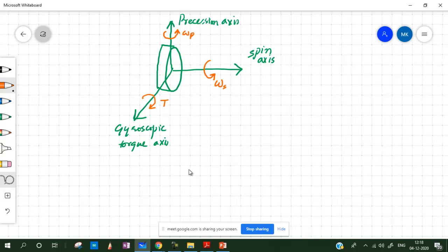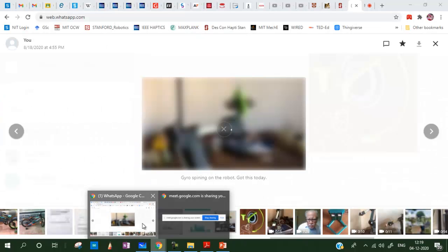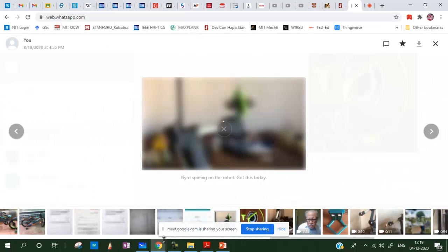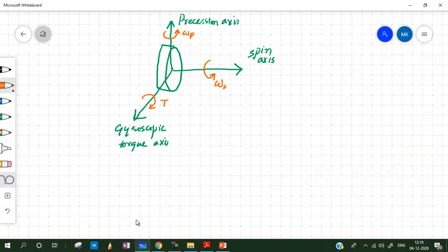Anyways, basically whenever, जैसे मैंने कल कहा था, if there's a body which is moving linearly and you try to change its direction, so you need some force to change its direction, isn't it? Similarly, if a body is rotating continuously, ठीक है, and then you are trying to change its direction of rotation, or you can say the direction of motion of the axis of rotation, it will resist that change in the direction of rotation, ठीक है, or you can say the spinning.